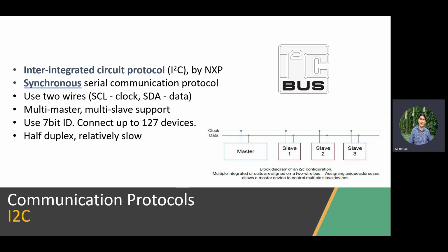The problem with I2C is a couple of problems. The first one is it only has 7 bits for addresses, which means for any I2C bus, you can only attach a maximum of 127 devices, right? So if you have a very big system, I2C might not be very common. Sometimes people get around this by having a hierarchical architecture, but it becomes a bottleneck problem. So they go away from I2C if you need a scalable system. Good. The second problem is it's half duplex because you have a single wire, so you don't have a separate transmitter and receiver. So you are either transmitting or receiving at a time, which means it runs at low speed, right? Its bandwidth is small.